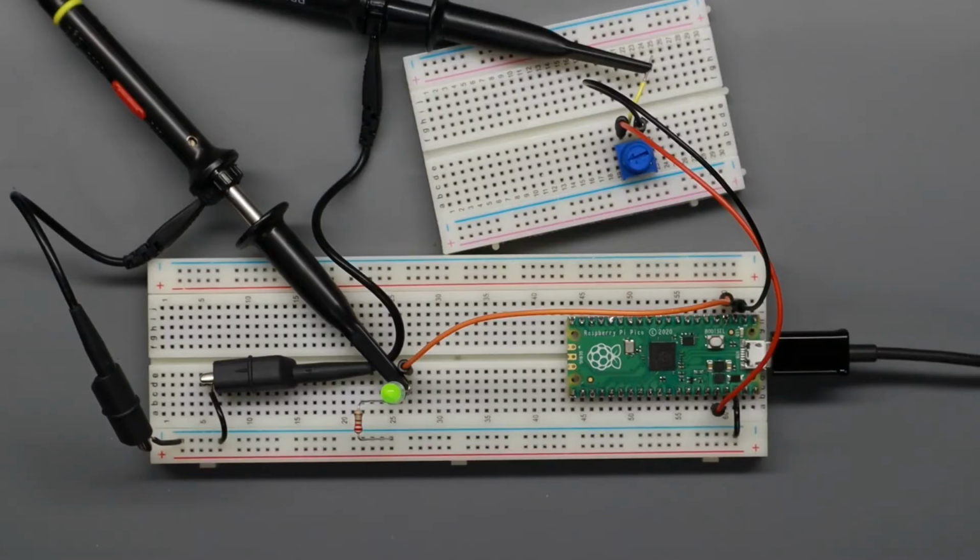Now that's an obvious flicker, and you would definitely not want to look at that for any period of time. It'd just irritate your eyes. Now imagine a motor being turned on and off at that frequency. It would be very damaging to all the power circuitry as well as the motor itself probably, because it's constantly starting and stopping. So that's the effects of changing our duty cycle too low.